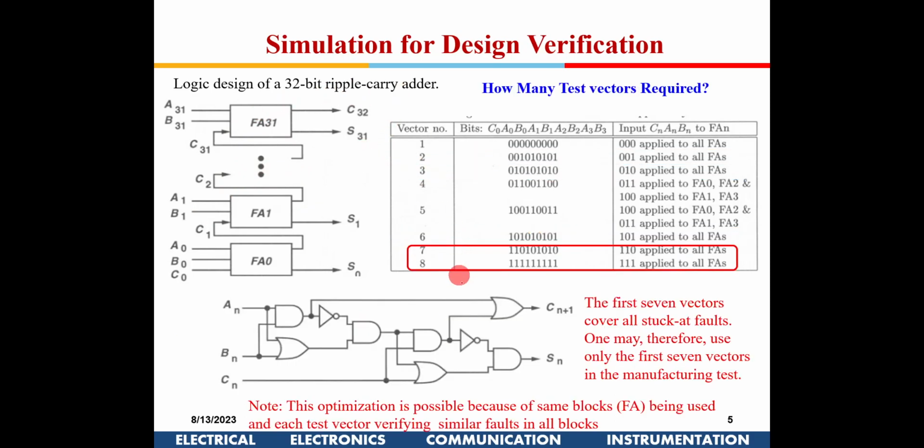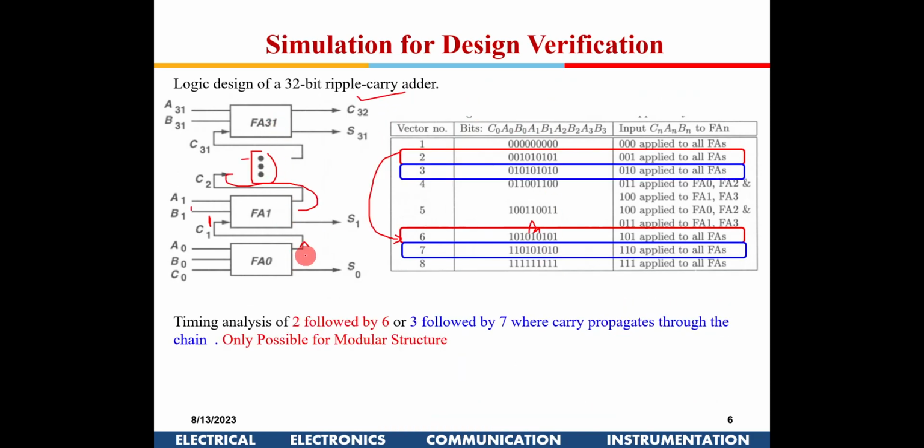So now first we do this logic verification, and if I have to do the timing verification, right? If I do the worst case timing verification also, at the end of it I will check all the outputs here, from here to here, 32 inputs, if it's matching, and then I move this test vector from 2 to 6, and within the stipulated time I check whether all the outputs are as per the desired thing, as per what is expected from the flowchart.